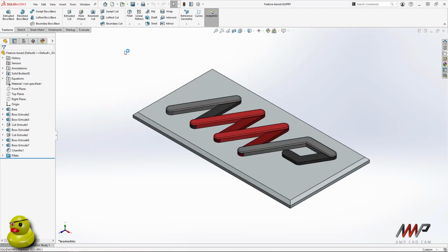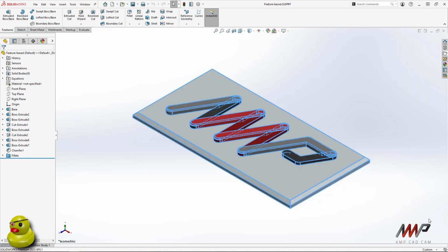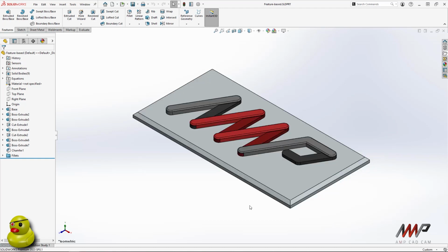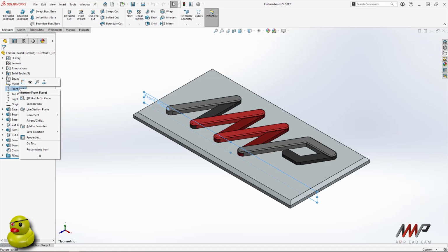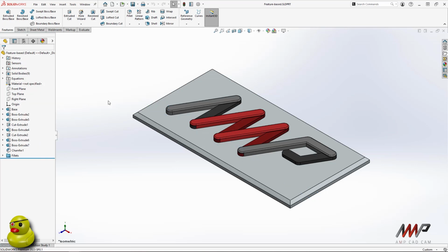In SolidWorks, the left mouse button is used only for selection. We can also use box selection, as is standard for Windows. Right-clicking on any item will activate the shortcut menu. This shortcut menu is context sensitive and will change based on the item on which you right-click. Our shortcut menu consists of our context toolbar and shortcut menus. Our context toolbar will also become available upon a normal left-click selection.